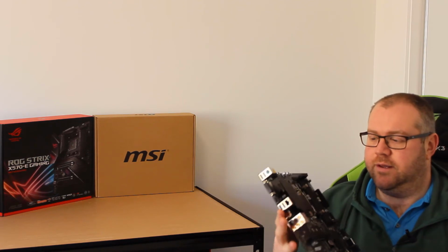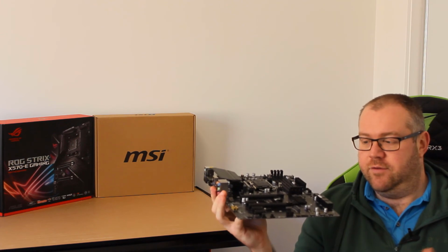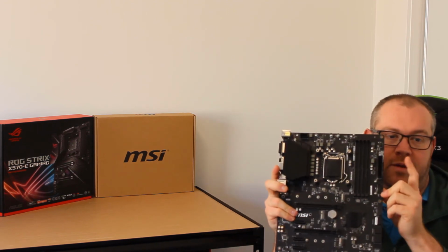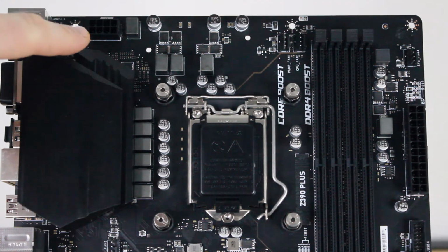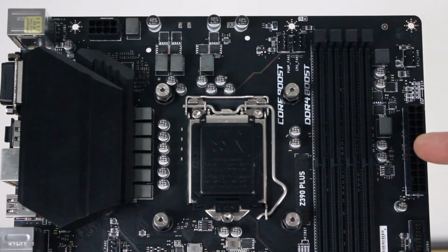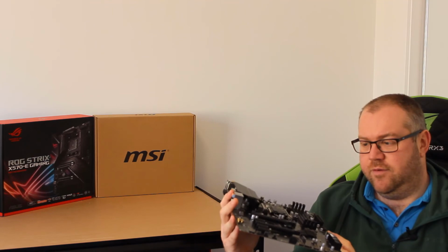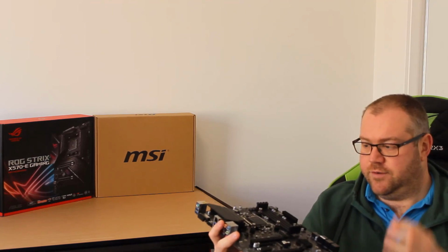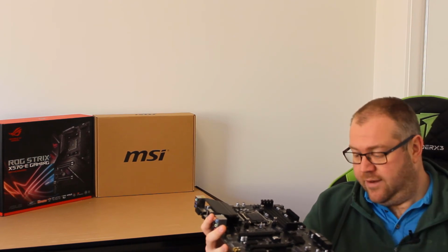What I want to do really quickly, and I'm going to get some close-ups of this for you to have a look at, every board, we're going to take a walk around this board. Every board will come with, number one, your power ports. So you've got up here an 8-pin power adapter that's directly for the CPU, so that's to power the CPU. Your 24-pin port, which powers the board. Then you're going to have, depending on which board you choose, a variety of different other options, or what we call headers.